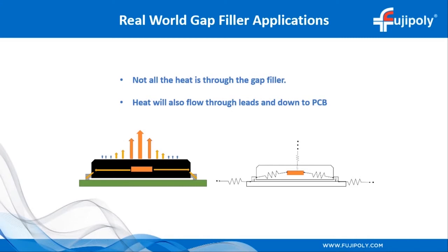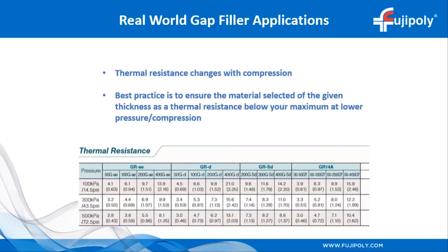Keep in mind that the heat is dissipated in multiple ways. Heat can flow down through the solder into the substrate material to help dissipate the heat. In addition, thicker layers of copper can be used along with thermal vias that will draw heat through and under the circuit board. We can also have convection if there's a fan in the enclosure.